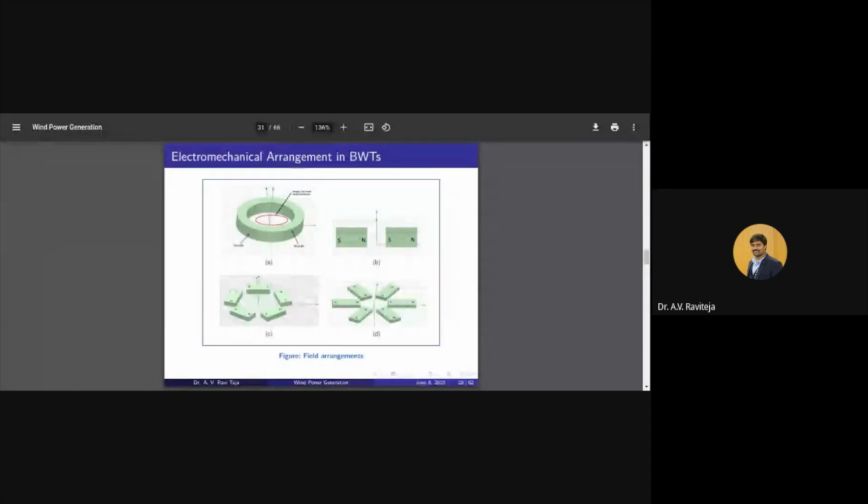So I should have a field perpendicular to any direction of motion, and a strong field, so that if I place a coil either on the mast or in that field and vibration, I will have an induced voltage in it. Okay. So, with the help of the software ANSYS, we tried to analyze different combinations of permanent magnet arrangements, which will tell us how the field distribution is. So, what is the objective?